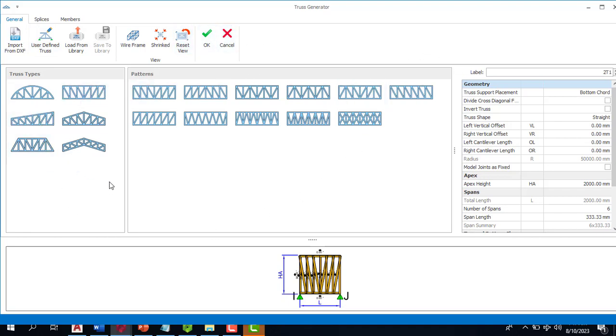But even at that, there are some steel patterns that may be a bit more complex than this, that is not going to be very easy for you to model directly from Protastructure. So you can simply import from DXF, which I'm going to be showing you in the next episode.